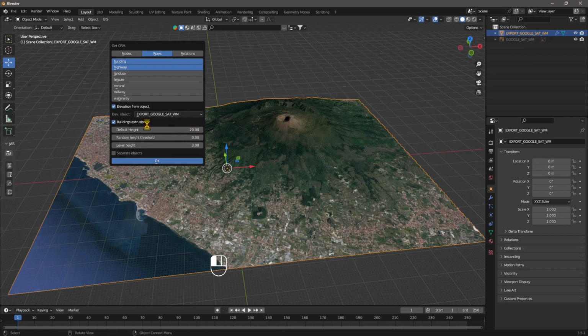Also here you can try with different parameters, but usually it will work. Now, if it crashes or it doesn't work, it's because there are too many buildings in there and the area is too big. So try to make it smaller. It's gonna take some seconds or perhaps also some minutes if the geographic information is too much. So just wait for a couple of minutes and see if everything works. Otherwise, again, try with a smaller area.